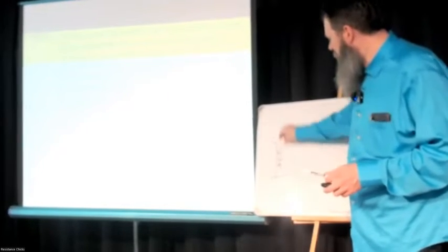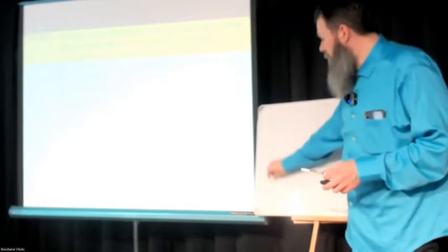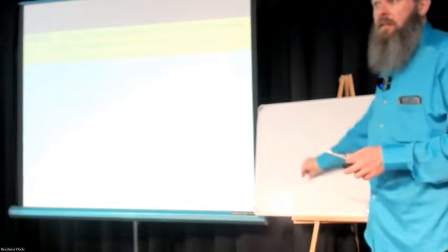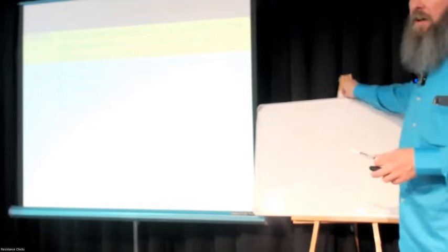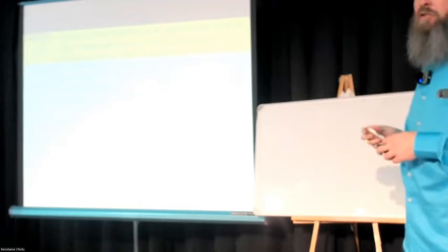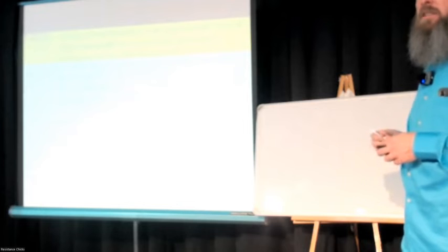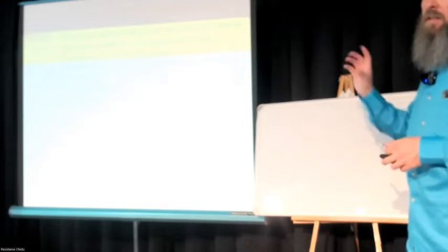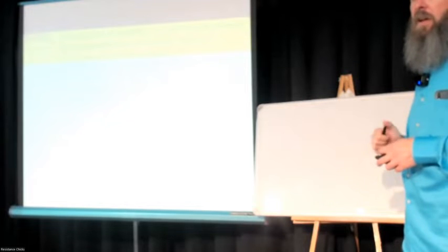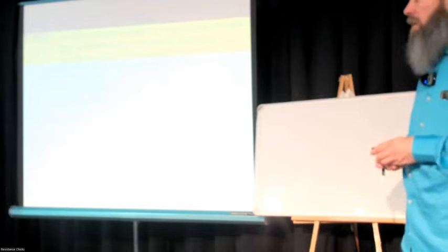So single sideband can be more, single sideband could be less, but they picked 3,000 because that sounds good enough that it's comfortable to listen to, but it doesn't take up too much space. If you had a 5,000 hertz single sideband, it would sound even better, but you'd just eat up too much space.